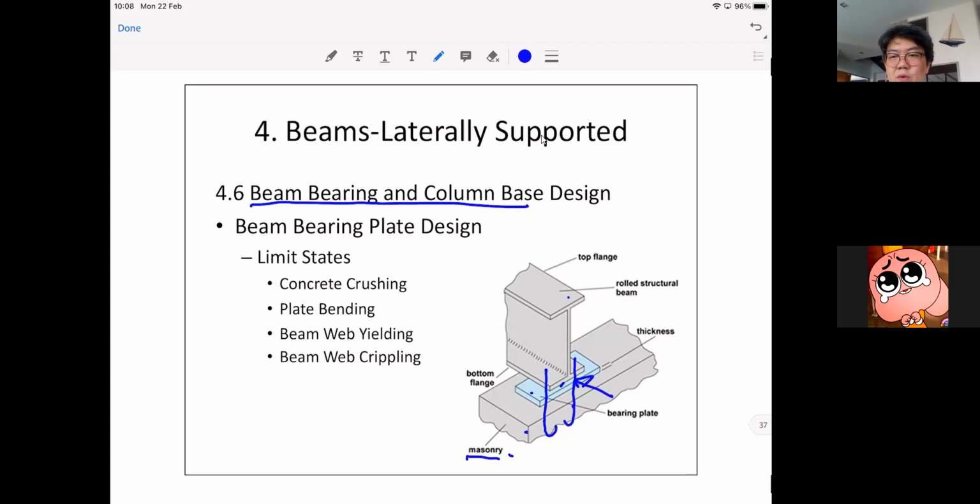Now the anchor bolts, there are two types of them. The one that you install prior to the construction, which is the best if you could. That means you must know the location of your beam exactly, and therefore you embed the anchor bars before you cast the concrete. But that has to be done before you cast the concrete. This is not my stuff, but it's for your own knowledge.